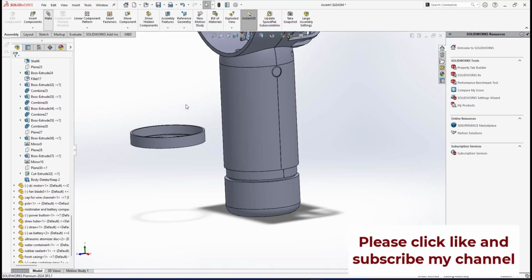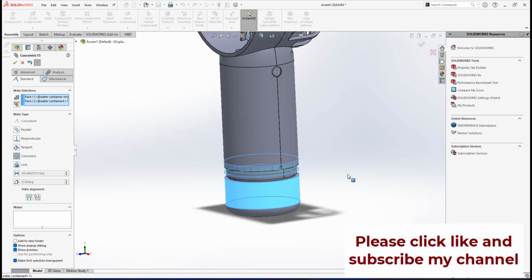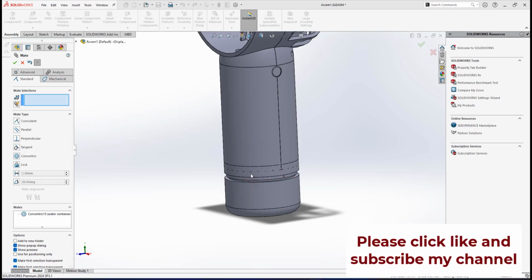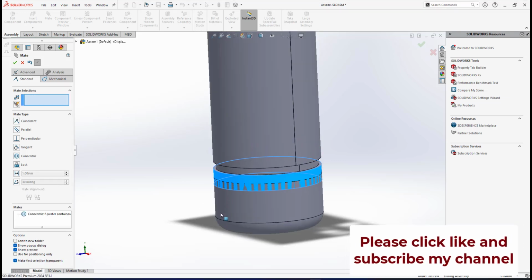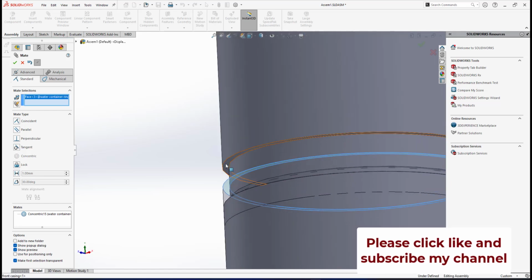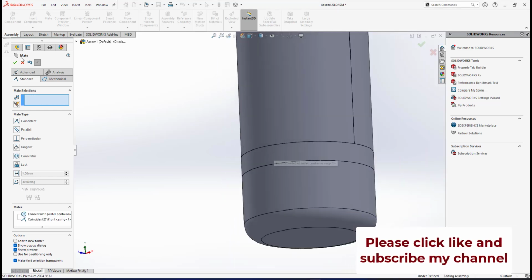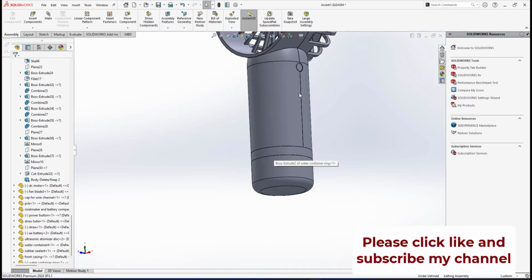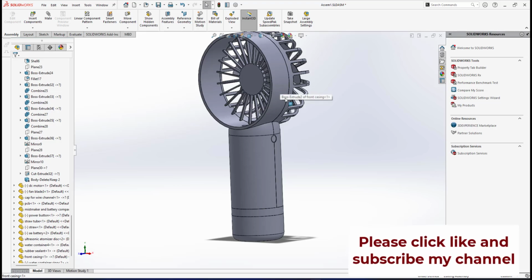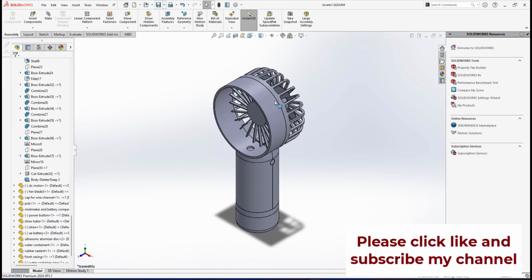Okay, the mate will be the cylindrical surface will mesh with this one. Then I can still drag the ring like this, and this face touch this face. Now the ring is in position. Then I click OK. Then let me go to standard view, save my file again.